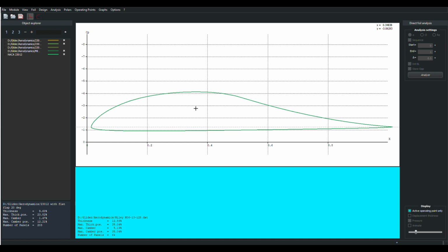And what they do here is they're delaying the transition to a turbulent boundary layer. They're keeping laminar for as long as they can. And then they're doing the most rapid pressure recovery possible without causing separation to occur. So they trip the boundary layer, it goes turbulent, and we recover the pressure as fast as we can without having separation. Those are the criteria that are set in the programs that generate these airfoils. And it produces these interesting results.